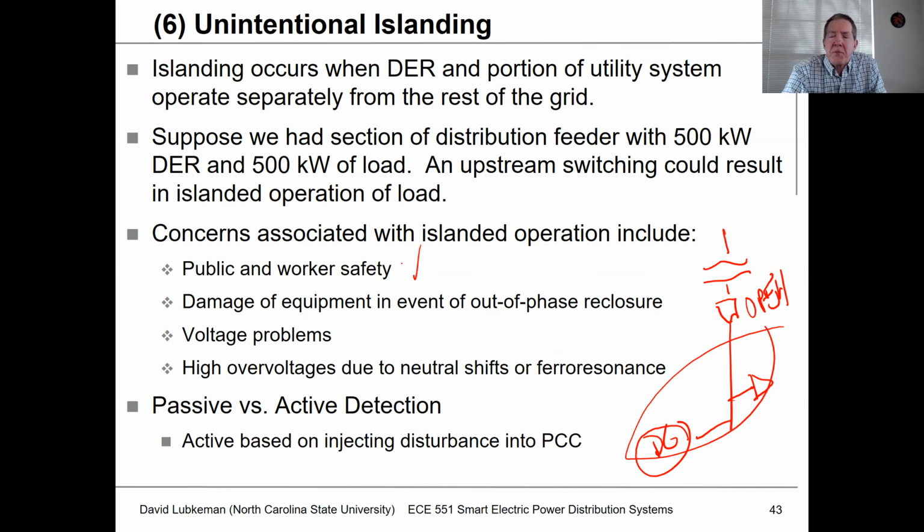And so if DG loses connection to the grid, and it is not designed to be operated in microgrid mode, we need that DG to drop off, to trip. And so there are special islanding algorithms written into the relay code of the DG in order to trip that DG offline.